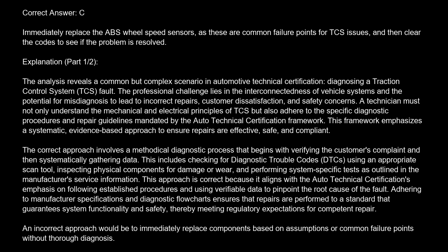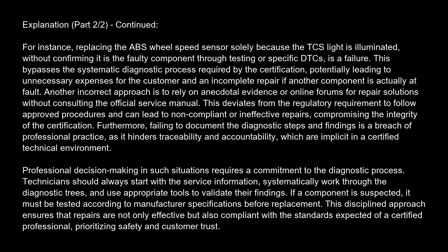Adhering to manufacturer specifications and diagnostic flowcharts ensures that repairs are performed to a standard that guarantees system functionality and safety, thereby meeting regulatory expectations for competent repair. An incorrect approach would be to immediately replace components based on assumptions or common failure points without thorough diagnosis. For instance, replacing the ABS wheel speed sensor solely because the TCS light is illuminated, without confirming it is the faulty component through testing or specific DTCs, is a failure.